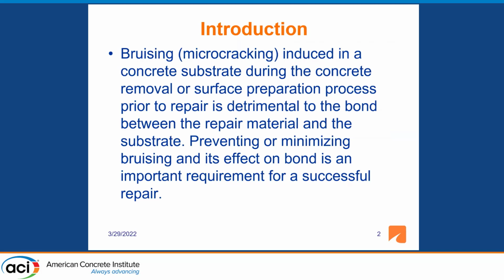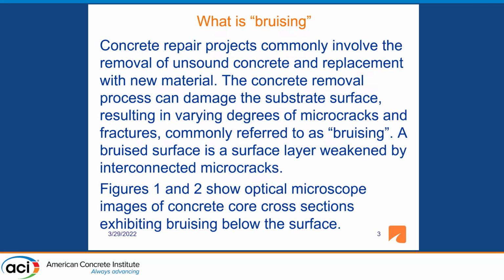Preventing or minimizing bruising and its effect on bond is an important requirement for successful repair. So what is bruising? Repair projects commonly involve removal of unsound concrete and replacement with new materials. The concrete removal process can damage that substrate, resulting in various degrees of microcracking and fractures. And this is what is referred to in the industry as bruising.